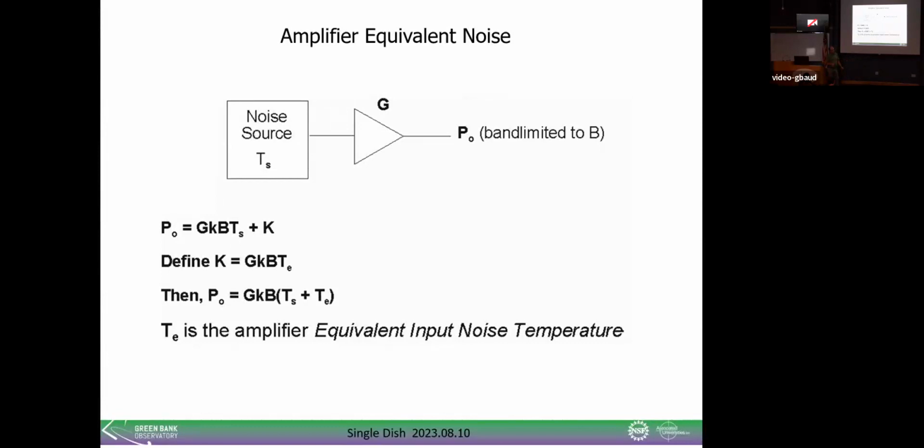So after you multiply the amplitude of the signal after the low noise amplifier, you can come into the room temperature components, and that is shared among the different receivers. We have a common IF, but you have to have the amplifier in each band cold and with a low noise temperature that fits the bandwidth of your feed to optimize performance.